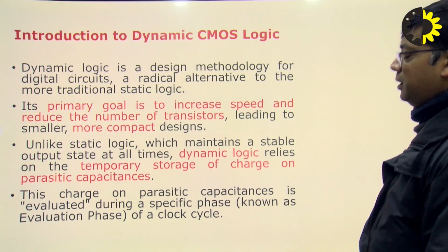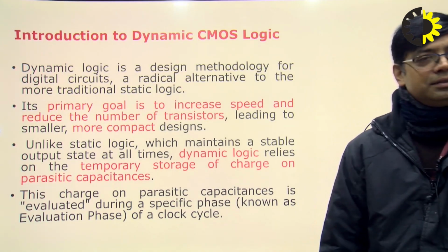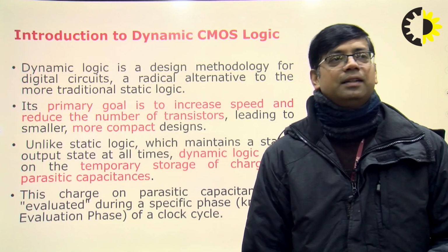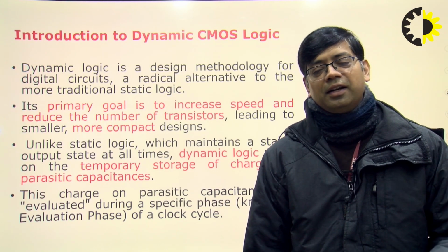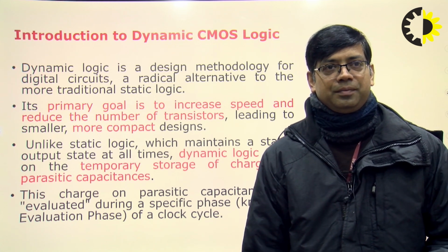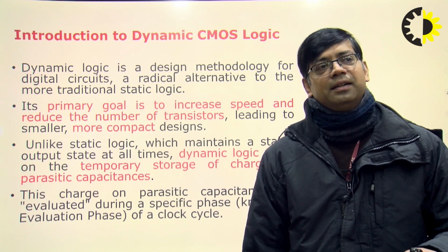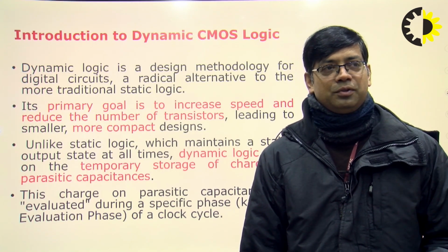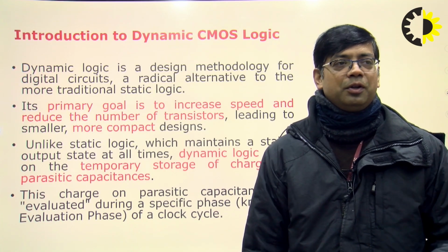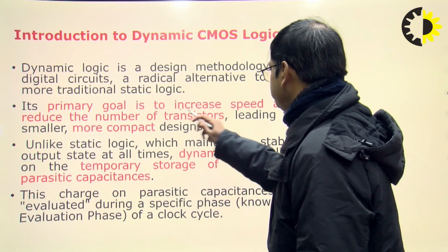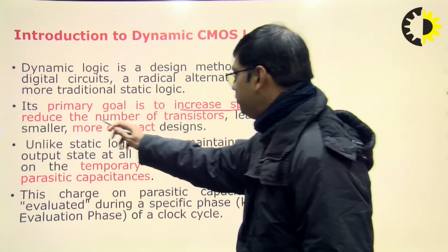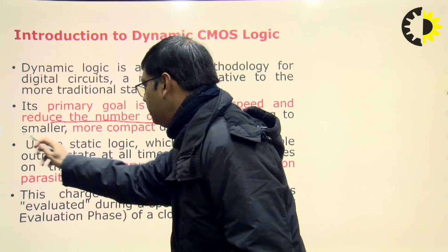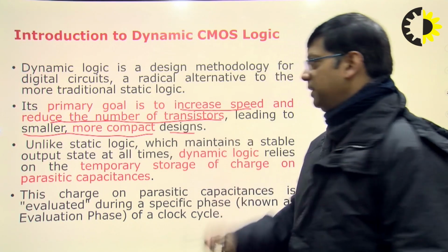Introduction. Dynamic CMOS logic is a design methodology for digital circuits which is an alternative to static CMOS logic, and there are certain advantages of dynamic CMOS logic over static CMOS logic, such as its primary goal is to increase the speed and reduce the number of transistors, leading to smaller, more compact designs.